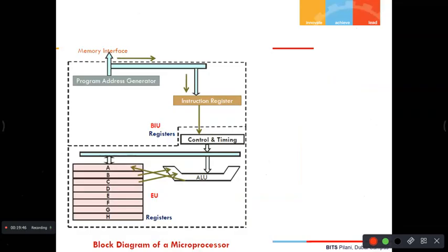And you also know about the universal shift register, where you can give parallel in, take parallel out, give serial in, serial out, you can give left in, left out, or right in, left out, everything can be done. Ultimately, it is nothing but storing zeros and ones and also shifting those zeros and ones right or left. You have done these registers in your previous semester in digital design, yes or no? Yes. It has a direct application to microprocessors even today.